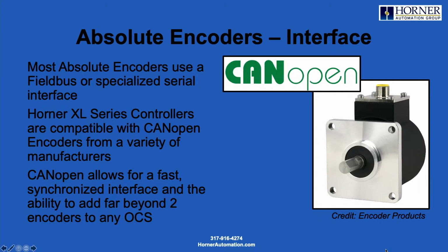You'd have 16 electrical signals passing from an absolute encoder or resolver over into a PLC type device. Well, this is 2020. We don't have to do that these days. Now we have a variety of serial interfaces that are available and field buses, which are terrific for this sort of thing, especially CANopen. A lot of you may not be that familiar with CANopen.